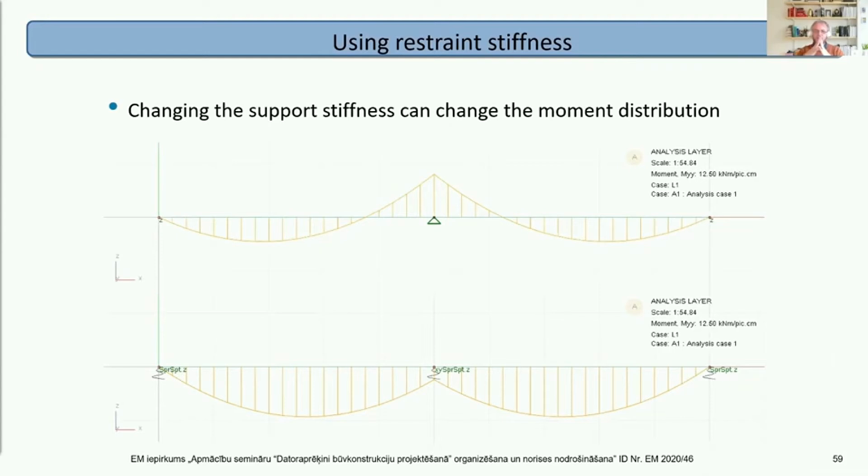The lateral torsional buckling is really dependent on the restraint. So the average beam is restrained on the top flange, let's say, and so the restraints will work for the sagging moments, but not the hogging moments. For example, if you've got a slab on the top of the beam. So in this instance, it might improve lateral torsional buckling behavior if it was analyzed for.